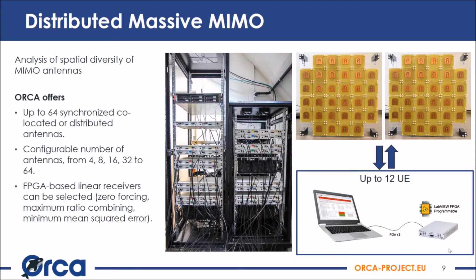The antennas for the base station are patch antennas. There are 64 antennas in the whole system, grouped into two arrays. Each array contains 32 antennas, and the number of antennas in a group can be configured, ranging from 4, 8, 16, and 32, and eventually 64 antennas.